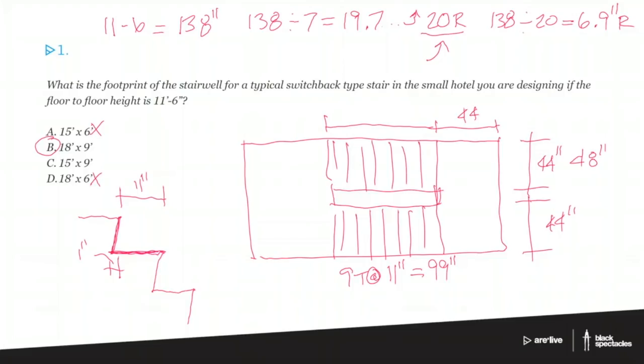And the reason that you do that angle and not the old school version where you have a little lip like that is that little lip, if you imagine somebody coming up with their boot, somebody with very thin ankles wearing a boot, that little spot right there becomes a trip hazard. So from an accessibility standpoint, these angled risers are more typical. There's a few other ways you can do it, but the classic is that angled for like a concrete stair or something, or steel stair.